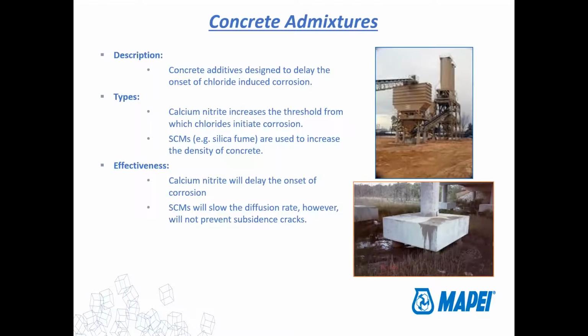If you're on the front end designing new concrete or using a fresh bag of repair mortar, this is just a good, cheap way to slow things down and buy yourself a little bit of extra time until the corrosion starts to happen and, frankly, becomes more of an issue. So it's not really a product that's going to prevent corrosion. It's just going to slightly delay it, but it's very cheap and easy to do. Frankly, I would like to see it done on every batch of concrete that we do. It'd be great, because it's easy to do, it has minimal effects on the performance of the concrete, and it just buys you that little bit of extra time.